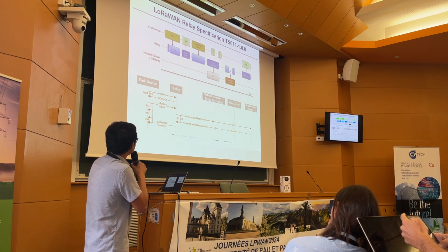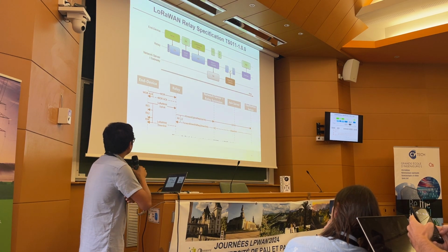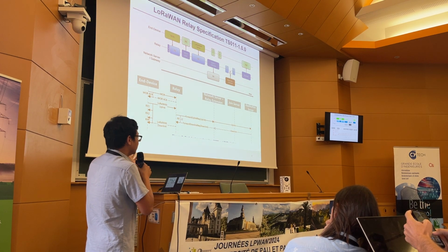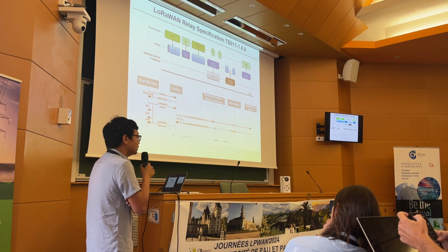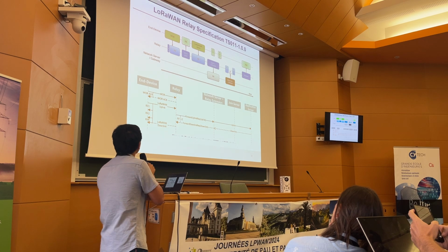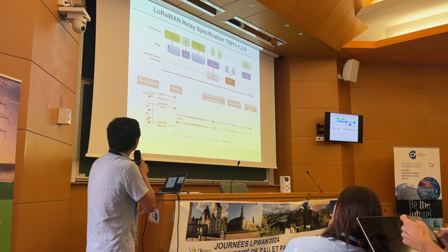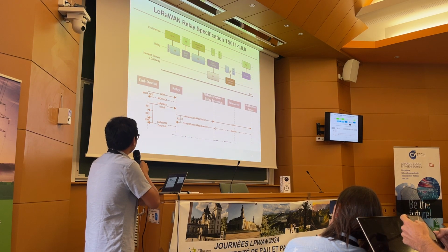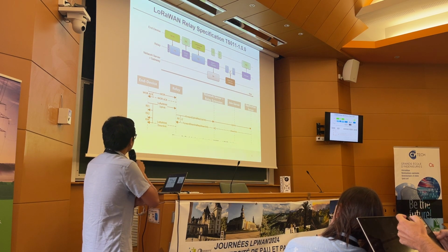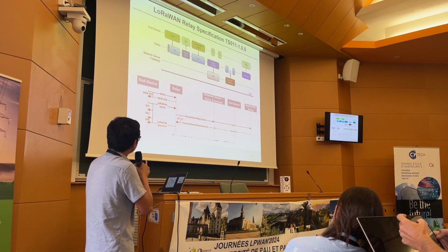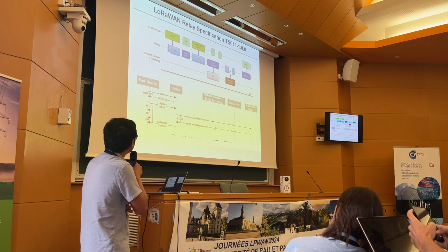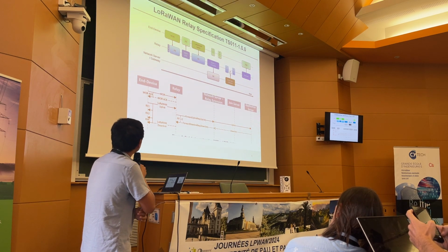Basically, this specification is the synchronous like LoRaWAN radio, a synchronous between the end device and relays. The LoRaWAN radio uses a long preamble, 1 second long, that can be received by relays, while relays continuously implement CAD, which stands for channel activity detection.